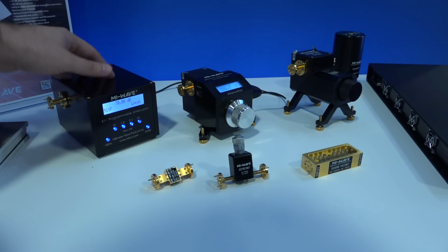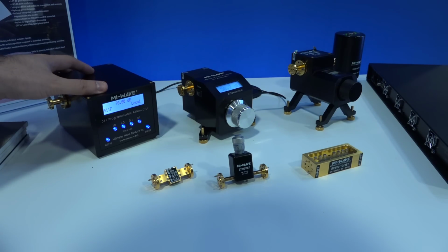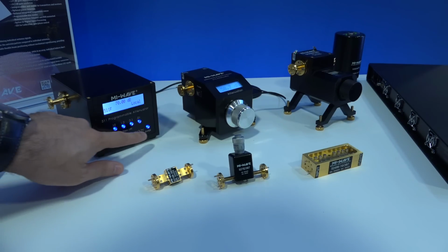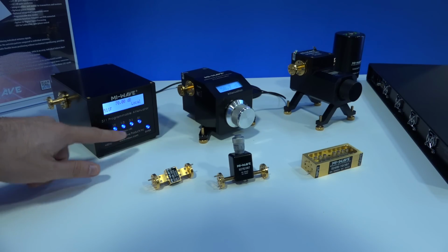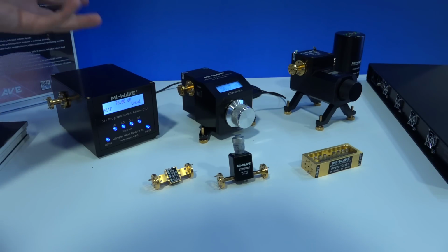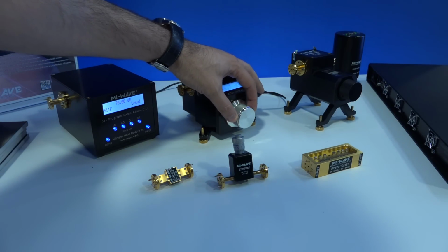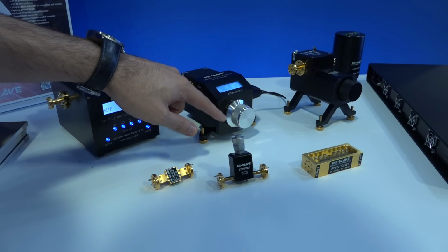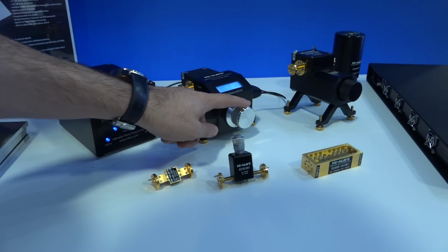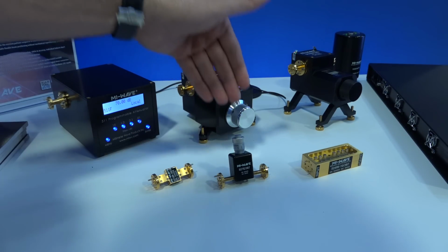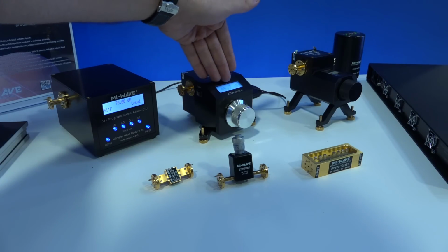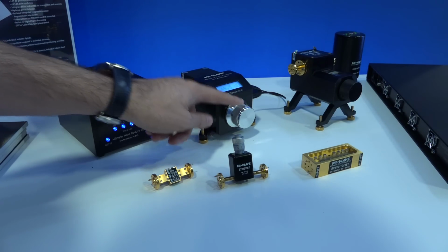This is a W band, but they go all the way up to J band, which is kind of crazy to think about, that you will be able to have controlled and repeatable attenuation adjustments. And because they're waveguide based, it also makes your entire setup, of course, much more predictable. You can also have a manual one. So this has a readback directly from the location of this. So this is an optical encoder, most likely, driving the plunger, the micrometer inside, and you get a direct readback, so you can quickly adjust the attenuation. Very nice.